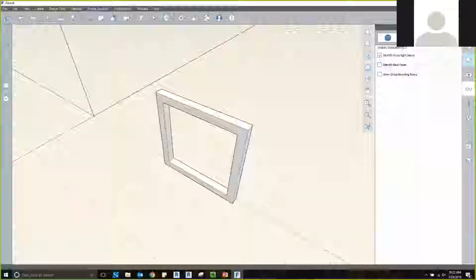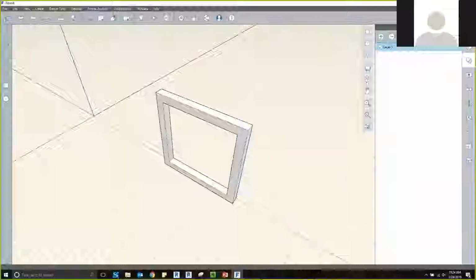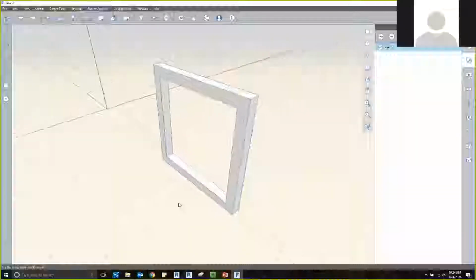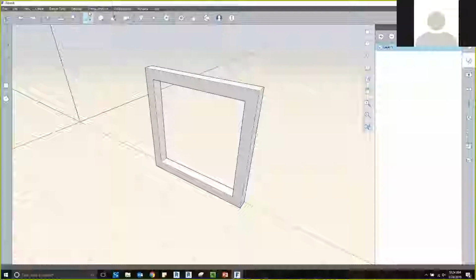One of the things that I mentioned before was layers. So we need to make sure that we are creating proper layers for this to be placed on. Unfortunately, within FormIt, you cannot begin drawing on a specific layer. You must tell the item after you have drawn it which layer it wants to go on. So now, just like any other layer properties that you all are probably familiar with, we can turn that on and off very easily.